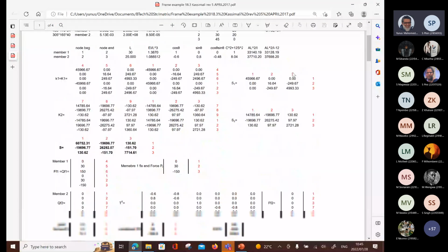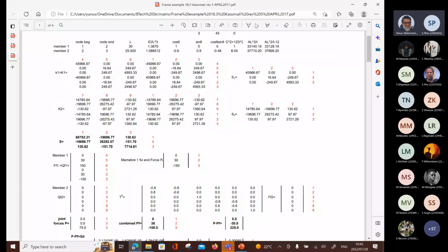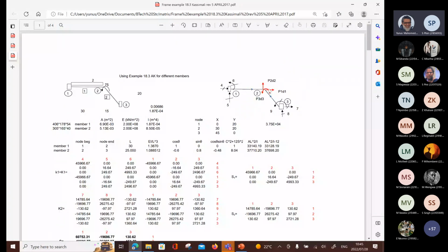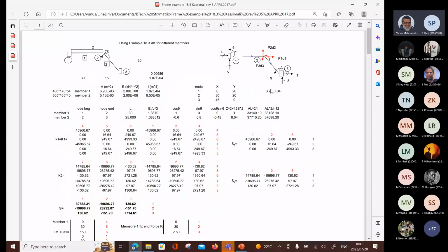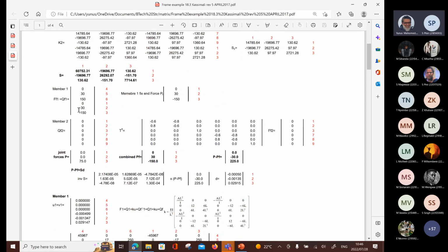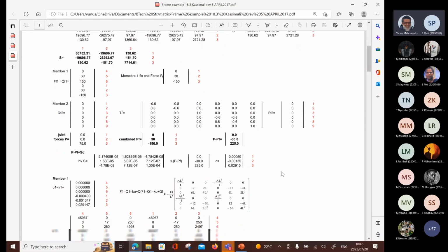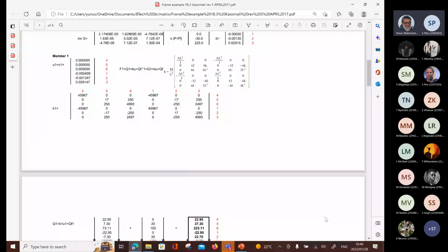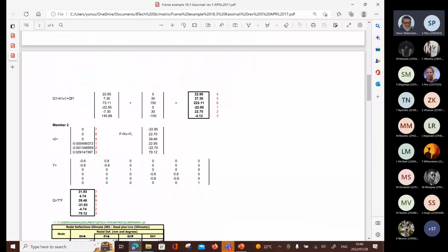So then I set up stiffness matrices for each one. One member is a 6x6 matrix, and then I extract what is common to both members, because I'm looking at resolving that connection at 2, and I'm able to establish the stiffness matrix for the joint. Then I look at the loads and pull out the loads, and then the associated calculations, and it goes into solving for that. And at the end, using matrices, of course, I'm able to get out the results.